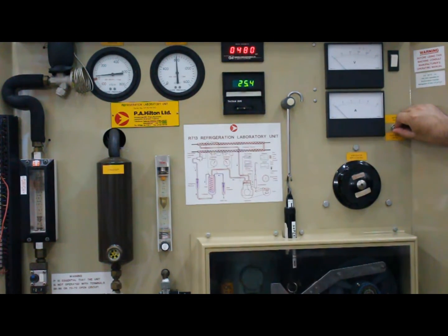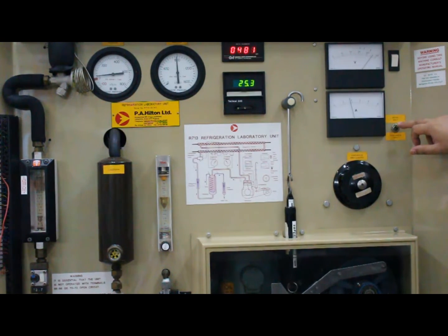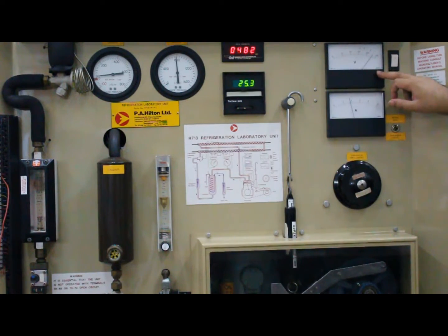But if it is switched in the upward mode, then it is showing the motor input that is being supplied to the compressor. In this case, the energy that you are using for the compressor working, you can calculate by using the product of the readings available on the voltmeter and the ammeter. But all the experiments that you need to perform are basically by varying the evaporator side input.